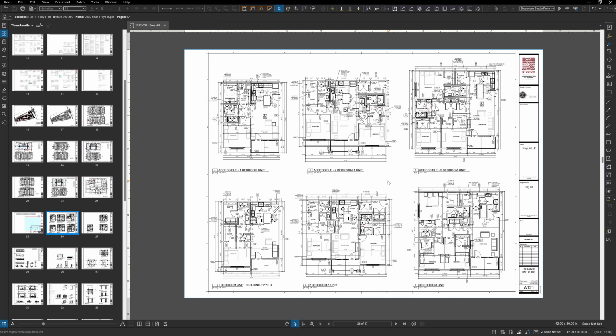Alright, interior, what is this? These are our enlarged unit plans. In general, I try to keep people from messing with these too much, because they can get you into so much trouble so fast, right? They are governed by a whole lot of ANSI Type B rules, and when it comes to the accessible units, the ANSI Type A rules.